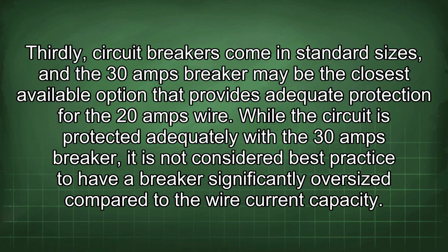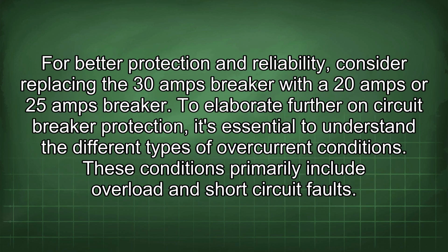While the circuit is protected adequately with a 30 amps breaker, it is not considered best practice to have a breaker significantly oversized compared to the wire current capacity. For better protection and reliability, consider replacing the 30 amps breaker with a 20 amps or 25 amps breaker.